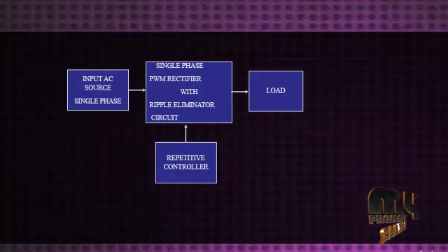Aluminum electrolytic capacitors are polarized capacitors whose anode is made of a particular metal on which an insulating oxide layer forms by anodization. Acting as the dielectric of the electrolytic capacitor, a non-solid or solid electrolyte which covers the surface of the oxide layer in principle serves as the second electrode, the cathode, of the capacitor.